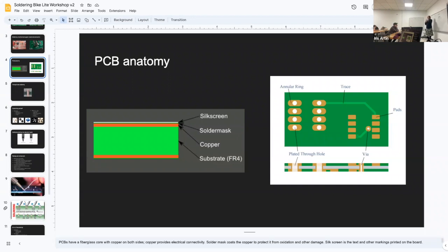It is this selective etching of copper on the two sides of the board that took the wiring that used to be outside the board and folded it into the board itself. That was the big idea in making circuit boards: to take the wiring and bake it into the board by using these very thin layers of copper, one on each side, and then selectively remove. That dates back to the 60s going to 70s.